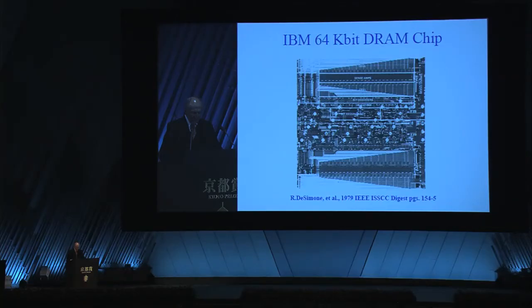I was asked to identify difficult challenges in the progression of my work. Just at the time the production of 64 kilobit chips was being announced, and the dynamic RAM seemed to be getting very mature, the world was becoming aware of two very significant papers. May and Woods of Intel and Yaney, Nelson, and Van Skyke of Bell Laboratories reveal that some 16 kilobit dynamic RAMs were suffering transient errors due to bombardment by alpha particles. The alpha particles were identified as coming from radioactive impurities in the materials of the hermetically sealed packages.